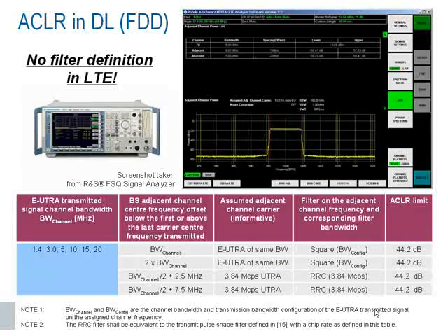In case of LTE FDD, first the presence of another LTE signal with the same bandwidth is assumed, second a wideband CDMA signal is available. The general limits are shown for both cases in the displayed table. Based on the used and tested frequency band, additional requirements in form of lower tolerances might be valid. This would be signaled to the UE via network signaling and needs to be verified during testing. Such tests can be performed using Rohde and Schwarz high-end signal analyzer FSQ, where the screenshot is taken from.